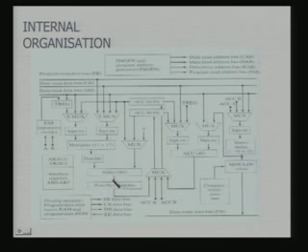In fact, the hardware that I was talking about, this is a special hardware block which passes through, and then it can be stored back to an accumulator, or it can be stored back to the memory also. This is a special compare select store unit which can look at the data and select MSW or LSW, which word to select depending on the size. I said that I can compare the most significant word or the least significant word, find out which was the bigger, and I can store accordingly. This is a barrel shifter which can do the basic operations with multiplications and other things.